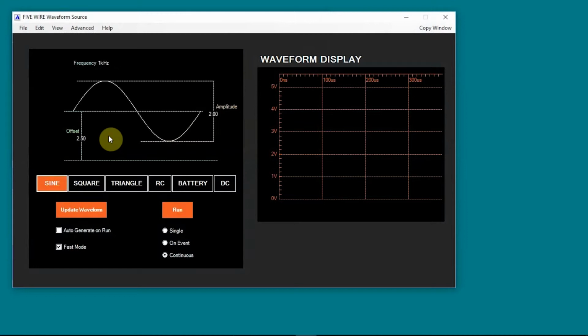It produces an analog output with a range from 0 to 5 volts and with a 10-bit vertical resolution. Up to 1020 analog points can be programmed. Each point includes its analog value and the time duration for the point.